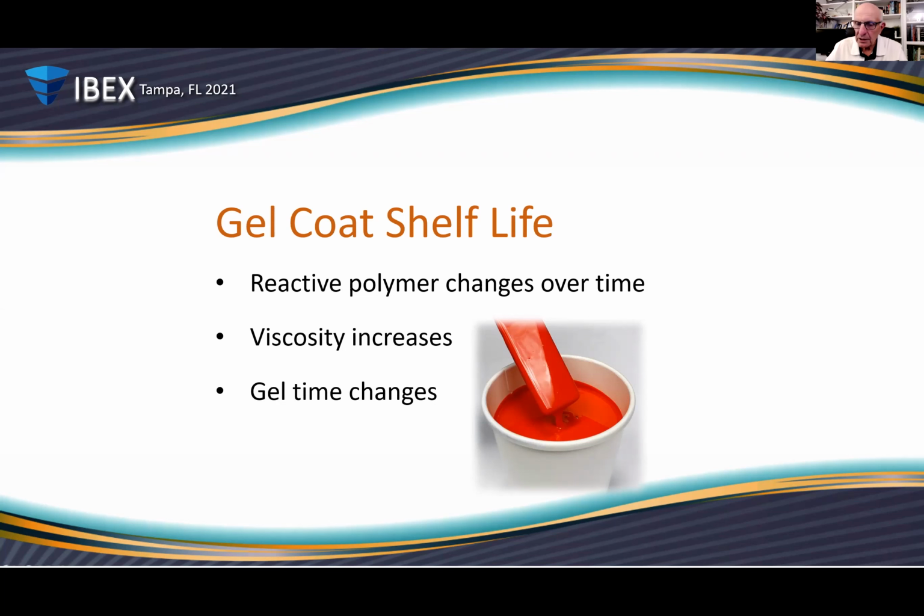So as time progresses, the viscosity of the material, and this goes for resin too, by the way, will increase and the gel time will change. Generally speaking, the gel time becomes longer. Not always, it sometimes depends on the formulation, but generally the gel time will become a little bit longer. So if you're using gel coat that is over its shelf life, depending on how far over it is, that will be some indicator of more potential for changes in the material from the original guaranteed specifications.